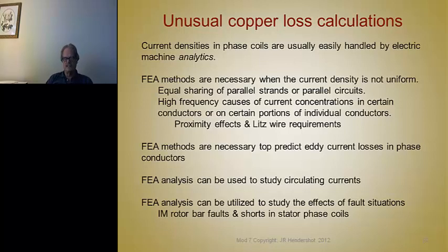And in the case of permanent magnet machines, if you get a transistor short or a ground fault short or a phase-to-phase short, you can use FEA to predict the results of that. This is becoming a very important topic for failure analysis of complex traction systems, for example. We've been asked to actually build motors with known faults in them, turn-to-turn shorts and phase-to-ground shorts. We've actually built little test motors for dynamometer kits that have those faults constructed in them, and external leads outside so they can be initiated, so that the students can model or test and compare with models what the results are of these kinds of faults.